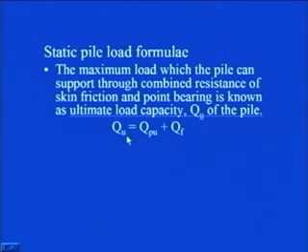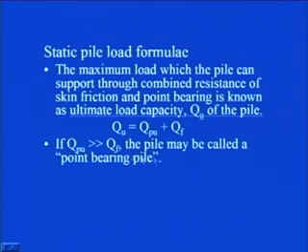So, you see here this QU will become equal to QPU plus QF. First one is ultimate point load, second is ultimate skin friction. If this QPU is quite high as compared to this QF, the pile may be called a point bearing pile.